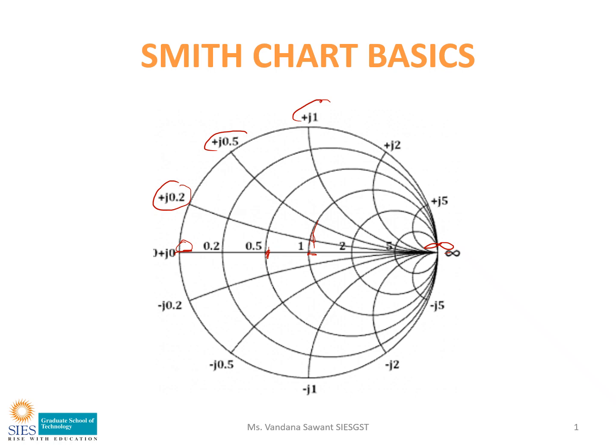Similarly, there are negative reactance values also, that is minus jX values. These minus jX values are represented by the vertical circles running from the bottom toward the center line. Likewise, there will be the minus j0.2 circle, the minus j0.5 circle, the minus j1 circle, and the minus j2 circle. These values also go on changing as we move from left to right, same as the plus jX values.